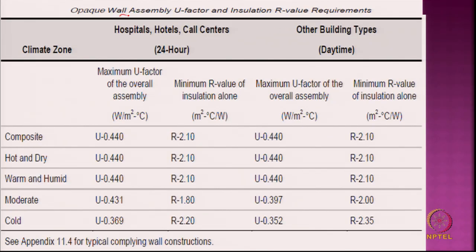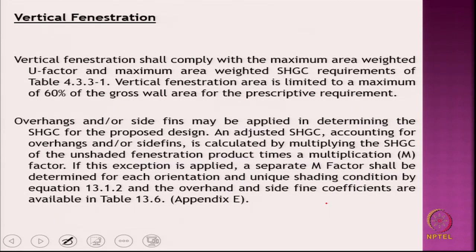wall assembly. Same for this climate, and these are the values for 24-hour and these are the values for daytime application only. So, this is how the prescriptive guidelines are given. Then it gives you maximum area weighted U factor for glasses.